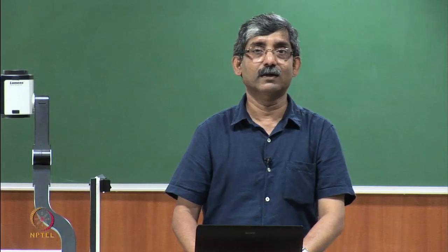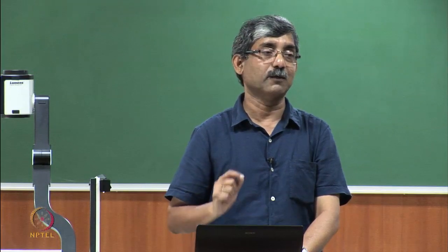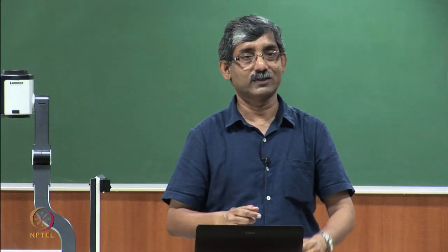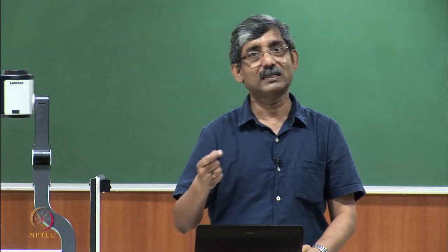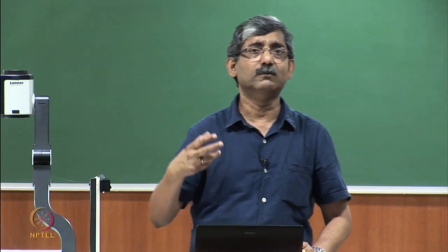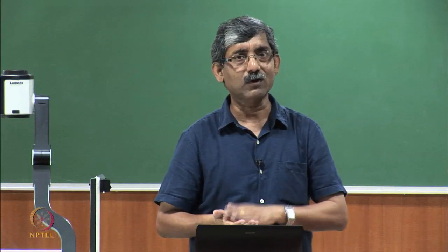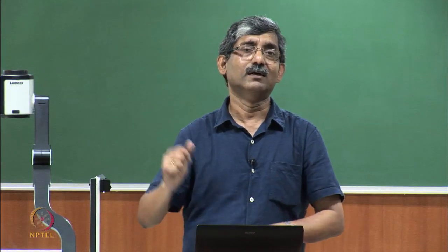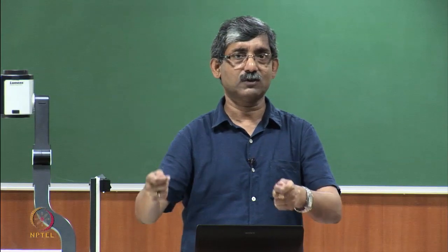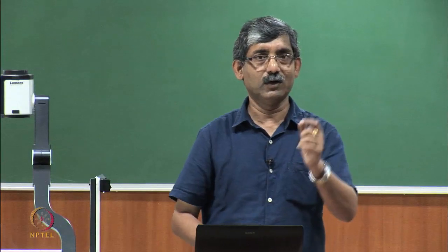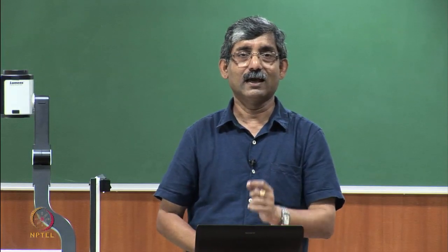This is done by an experienced person, and the problem here is that it is subjective in nature. Different classers will land up with different evaluations for the same cotton. So, this will give us a rough idea about the overall length of the cotton, but we cannot take any decision based on this result. It will tell us this cotton has a longer length, this one has a short length, but we will not take any action on that.